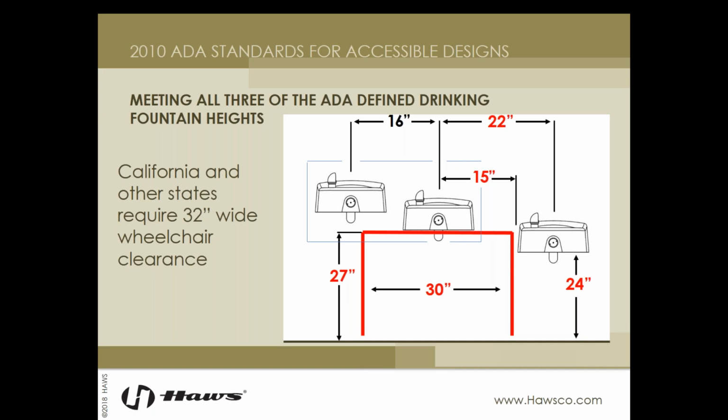But just because something is installed correctly doesn't mean it's compliant, right? If our stream height for our bubbler, for our water is off, our alcove depth is off, etc., we'd still have some problems here. But from an installation standpoint, this is spot on.